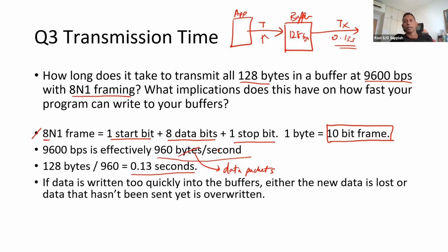What I would normally do is make the system generate an interrupt, in a way such that when I finish, I get a notification, so that the moment the notification comes in, I can proceed to load the next set of data to the buffer. That will be a more efficient and more accurate way of doing it.